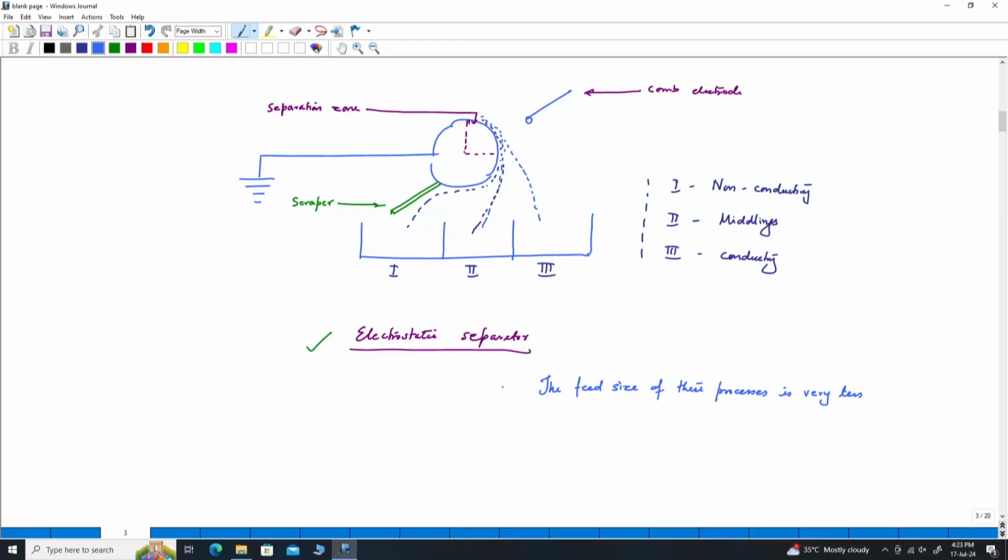But achieving a very fine particle size is going to require large energy, a large scope of working on the grinder unit, because it would require the reinsertion of the finished product back into the raw material, so that finer and finer fractions are achieved for separation using the magnetic separator or the electrostatic separator, because the feed size itself is very small. And this is the first disadvantage.